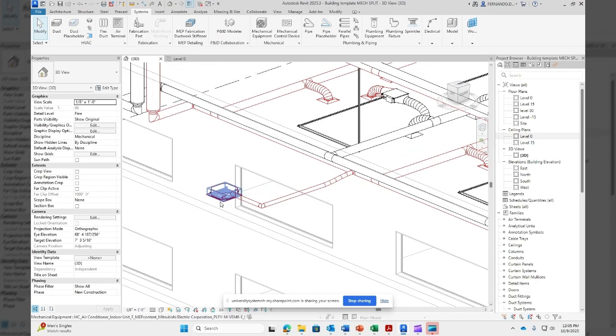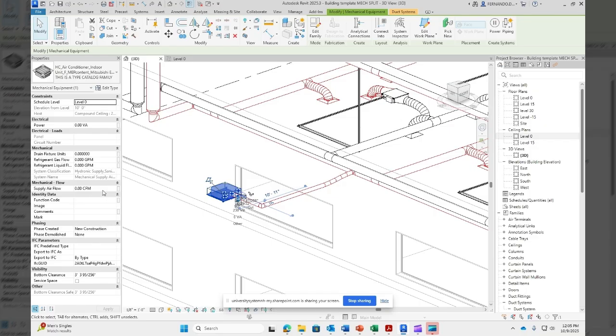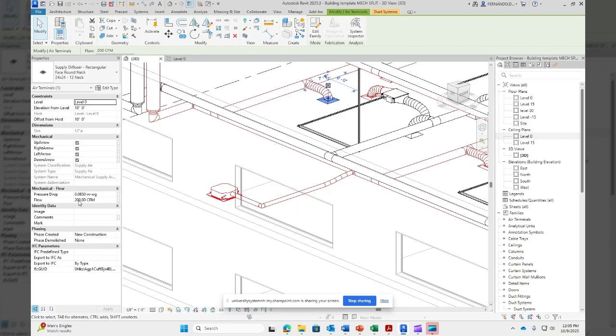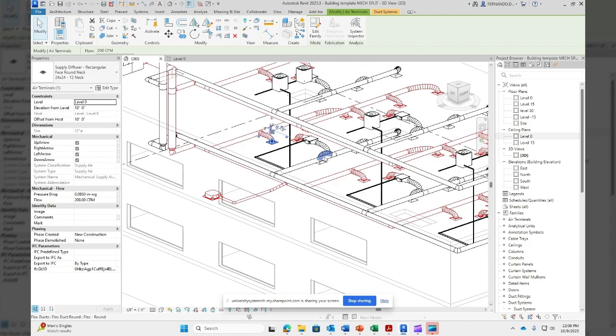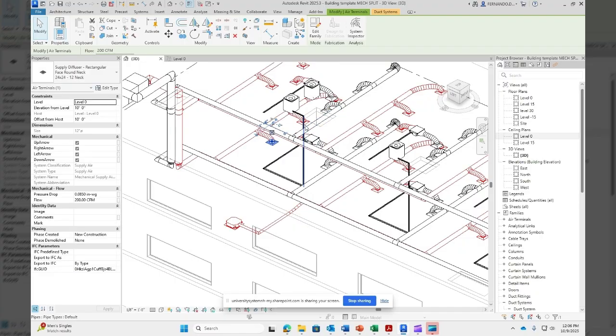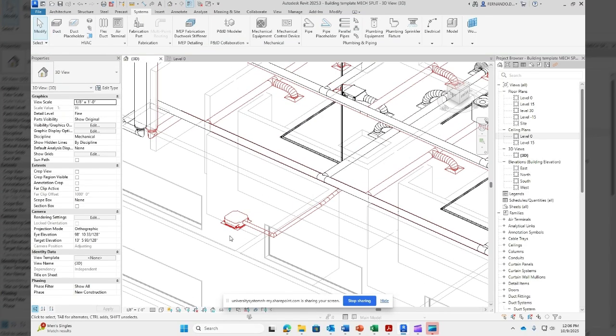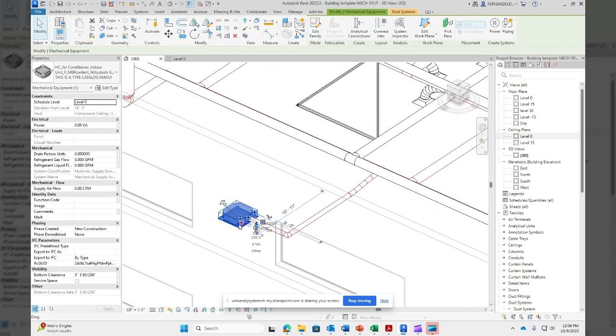Okay, I didn't change the airflow. This is now working as a supply. So remember that the supply has the airflow. In the class it's 600. That's why we have three supply diffusers with 200 each. In the office we have 5 people times 20. It's 100.